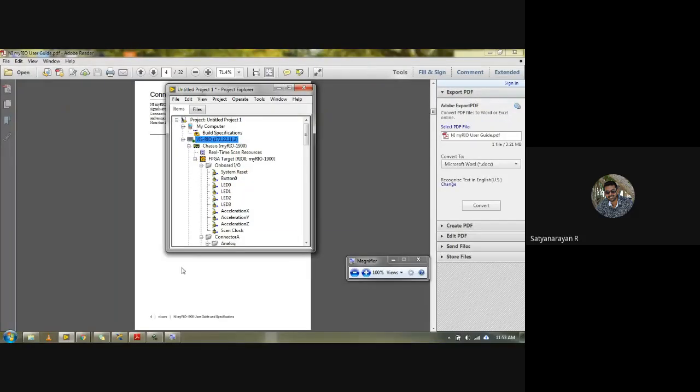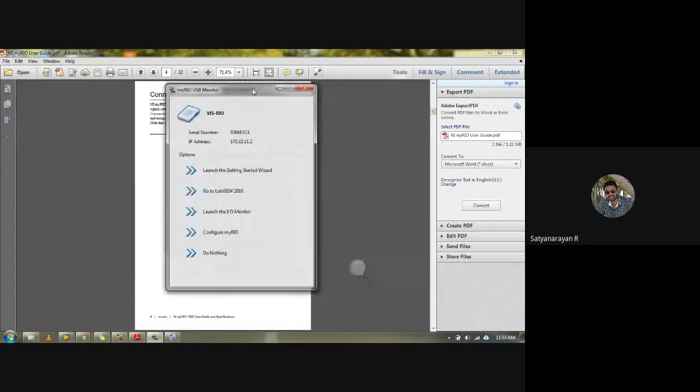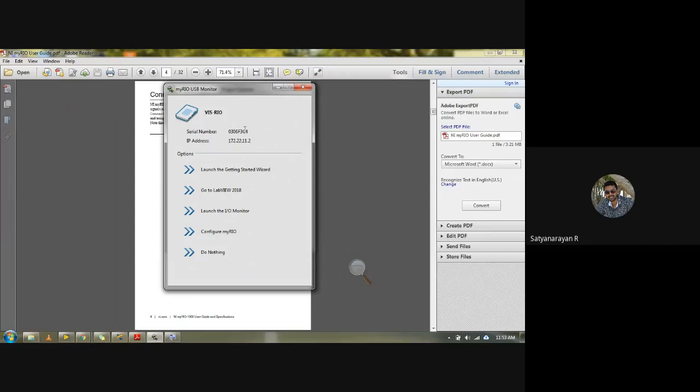Before getting into this, I would like to show you one more demo: how to check whether the hardware is connected properly, or how to test the hardware. I hope when I was explaining the MyDAC, I showed you the test panels, right? I connected a wire between analog acquisition and analog generation, AI and AO, and did a loopback test to show whether all my channels were working well. Similarly here, instead of connecting to the channels, we have very good features in the onboard devices like accelerometer, LED, and button. We'll glimpse those parts.